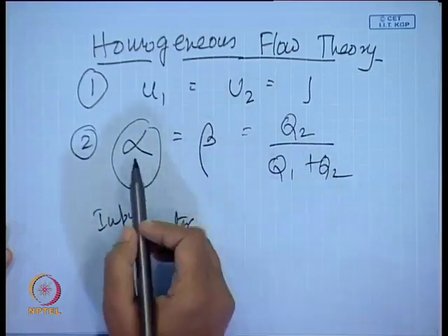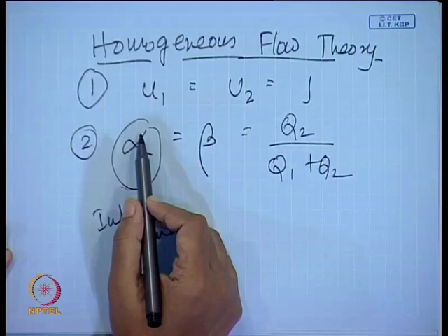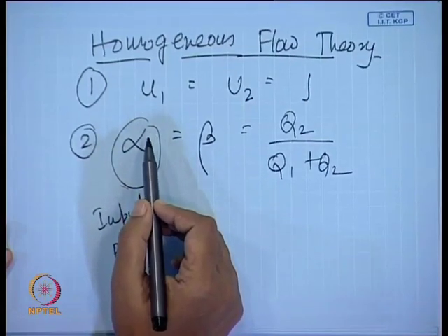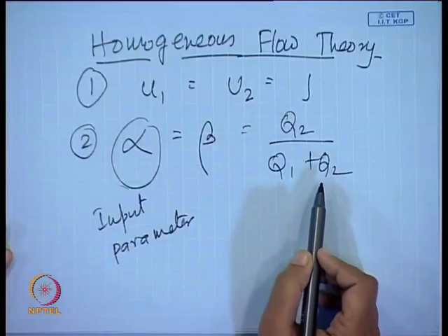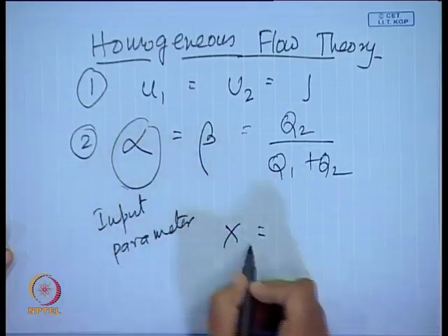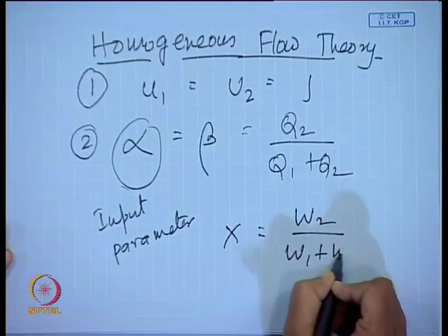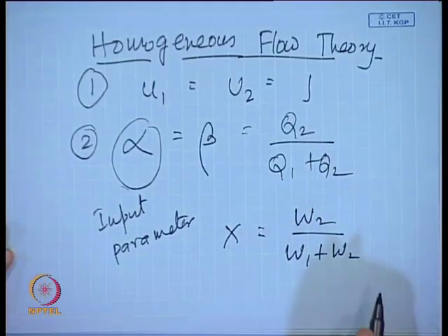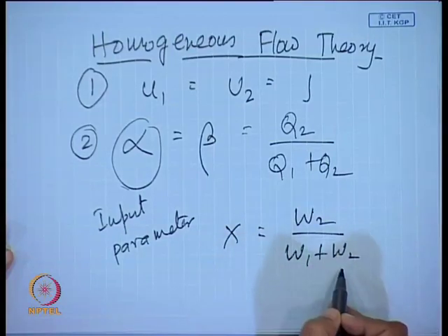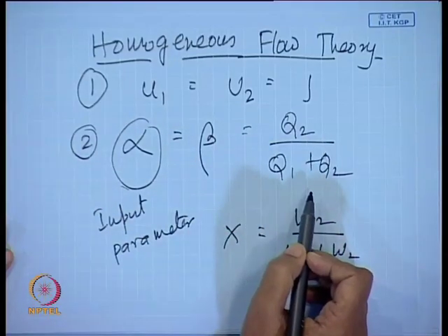The inlet void fraction and the in situ void fraction have become equal, or in other words the void fraction, the in situ composition, is nothing but a measurable parameter. Just for recapitulation, suppose there is evaporation, condensation or boiling, then we can obtain the quality from the inlet mass fraction, and the void fraction from the inlet volumetric flow rate.